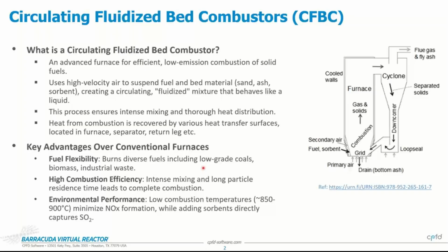So when you combine these, and if you can get the fluidized bed reactor to operate properly, you basically have a pretty high combustion efficiency for a CFB. Not only that, the combustion happens at relatively lower temperatures, which means there's less chance of NOx formation. And even if you do form some NOx, like I was talking about, you can always throw in some sorbents in the system to capture some of those pollutants even before they leave the reactor.